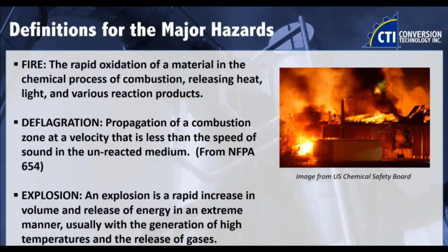So let's use flour. Flour is going through a dust collector. When those air pulses hit the bags, you do have small combustible particles that are present. Second, the particles are suspended in the air at a sufficient quantity or concentration.